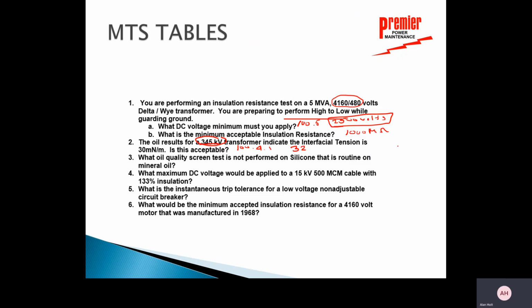And basically, that whole interfacial tension test is, if this is my beaker full of oil, I see that if I look at it from the side, it's not flat. There's a little curve there on the side, little meniscus it's called. But I actually try to drop a pin in there, and I measure the pressure pushing up on that pin by the interfacial tension of that oil. And that's the test that's run.